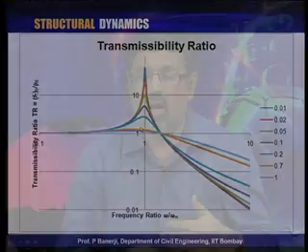Okay? So, the point that I am trying to make is that a design problem is really you are trying to weigh two things. Ideally, I would like to make the springs as soft as possible, then I don't put damping in at all, and transmissibility can be as low as possible. On the other hand, for operating reasons, if beta cannot be greater than root 2, then I have to put in a design with a huge amount of damping and keep it as soft as possible. In other words, as close to root 2, or make it completely rigid, so that transmissibility comes close to 1. Okay, so I think that is the force transmissibility problem.